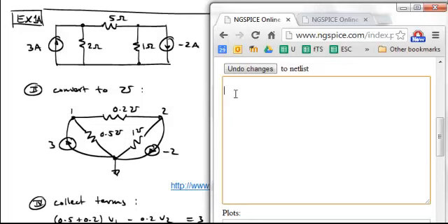So I'm going to demonstrate this by actually carrying out a couple of simulations. We're going to begin with example 1A. And what you want to do when you go to describe a circuit using a netlist is you need to have all the nodes numbered, and then you need to have all the elements numbered as well, which of course I don't have here, but it's a small enough circuit that I'm just going to tell you verbally how I'm going to number them.